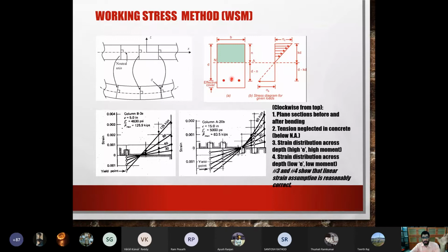where do you want to keep your reinforcement? Do you want to keep it where the compressive stresses are, or where the tensile stresses are, and why? By the way, anybody who answers, please tell me your name and answer so that I know who is answering. Sir, Varun. We have to put the reinforcement on the tension side to take the tensile forces, as concrete is weak in taking tension. Yes, so in order to aid the tension carrying capacity, you place the reinforcement at the bottom.